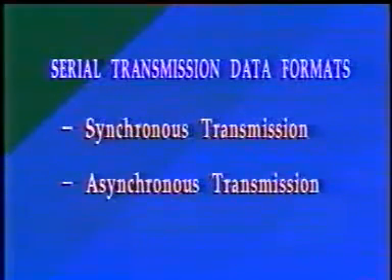So if the same data path is used for transmitting the different bits, then how is the receiver going to identify the beginning and end of a bit? How is the receiver going to identify the beginning and end of a byte? So for this bit and byte identification, special timing signals are added with the data and transmitted along with the data. Such timing signals are known as the synchronizing signals. Two different methods are used to add these synchronizing signals. Accordingly, the serial transmission is known as synchronous transmission and asynchronous transmission.